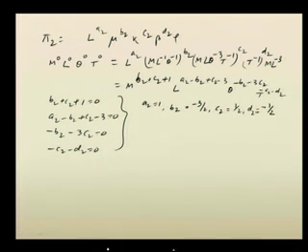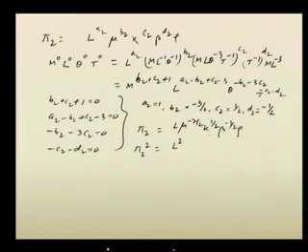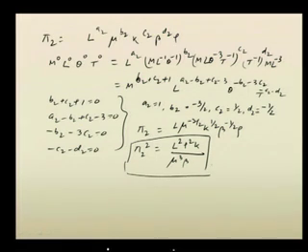So, the dimensionless group pi 2 becomes L mu to the power minus 3 by 2, k to the power half, beta to the power minus half, into rho. If we square it, pi 2 square becomes L square rho square k by mu cube into beta. I have just squared it, and this is also a dimensionless group. Directly this is not a very known dimensionless group, but once we go for the other one, we will see how things become important.